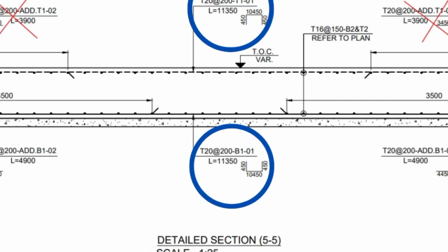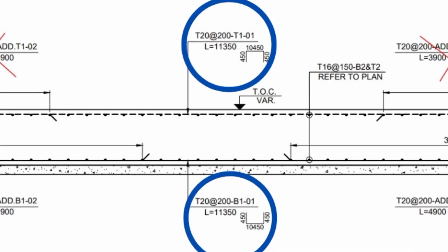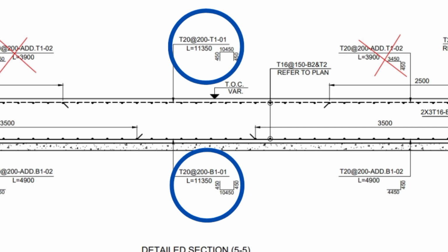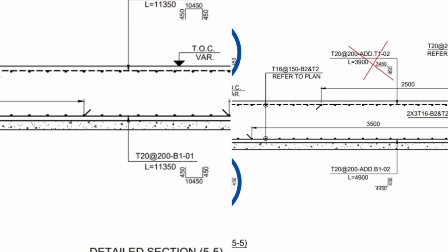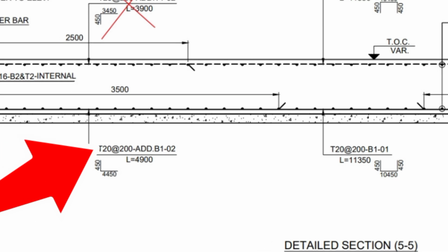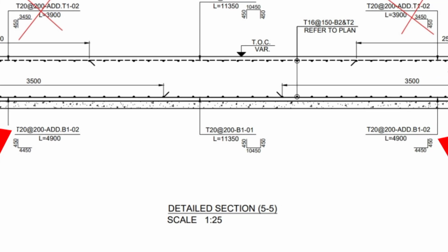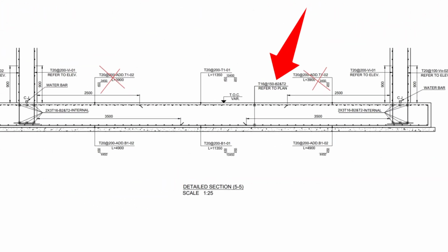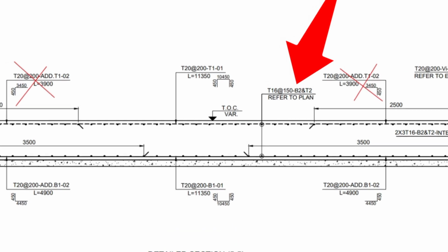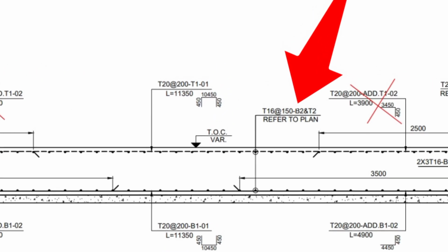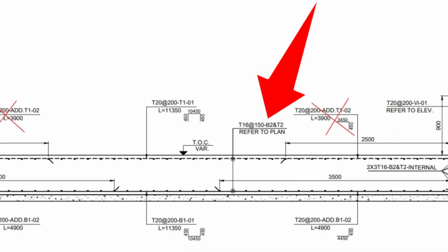The foundation steel reinforcement details show that the steel cover block in the foundation is 70 millimeters. The bottom reinforcement and top reinforcement have 20 millimeter steel bars with a spacing of 200 millimeters. The bottom 1 reinforcement has additional 20 millimeter bars with a spacing of 200 millimeters, which goes beneath both walls. The bottom 2 reinforcement and top 2 reinforcement have 16 millimeter steel bars with a spacing of 150 millimeters.